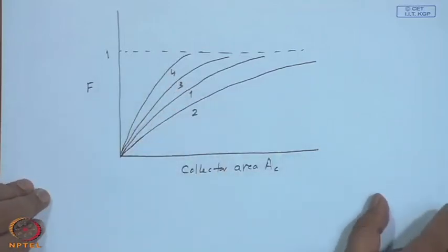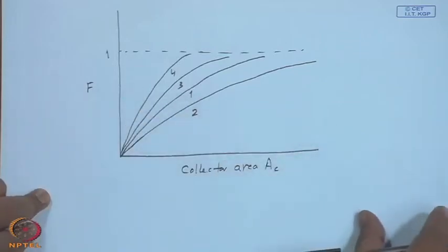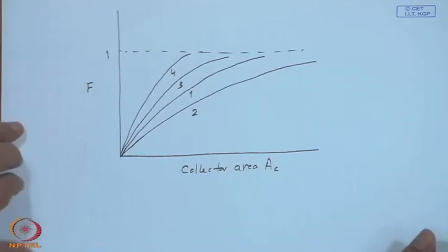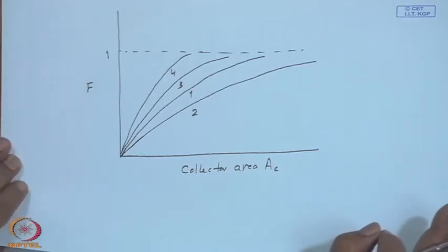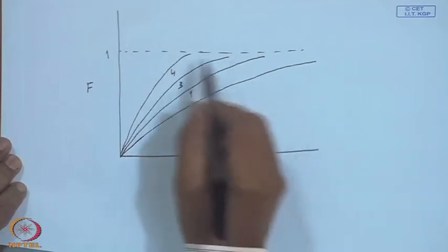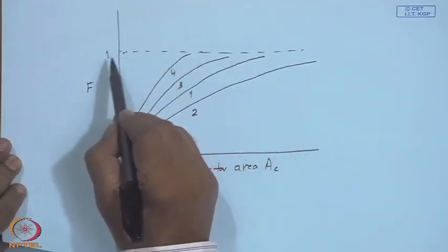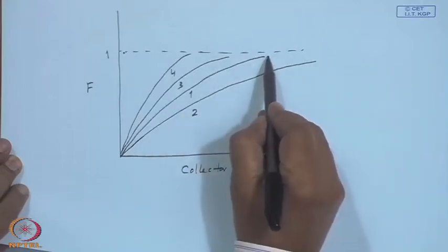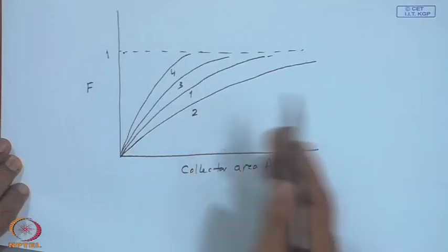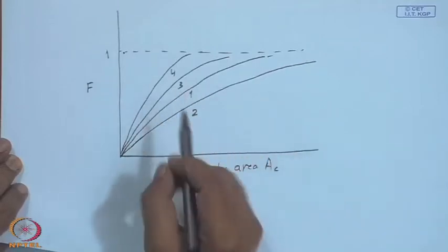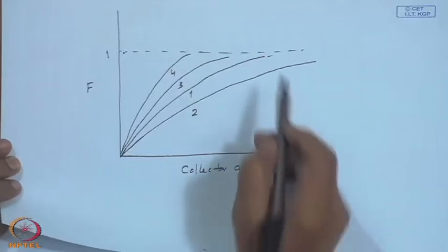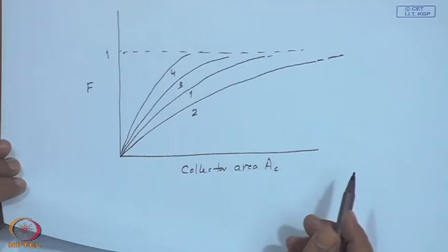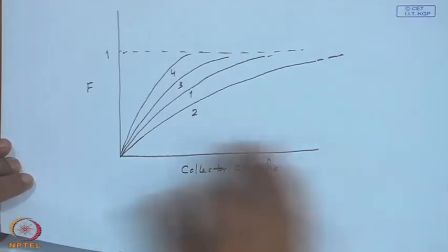So, this is deliberately not put monotonically. So, this is my solar load fraction. If the total load in the year is completely met by the solar energy system, it will be equal to unity, and it will approach unity for pretty large areas, because at times, without an infinite storage, you may not be able to meet all the load throughout the year. So, it will reach 0.9995 and may not be 1 all the time. Okay. So, this is the nature of the curve.